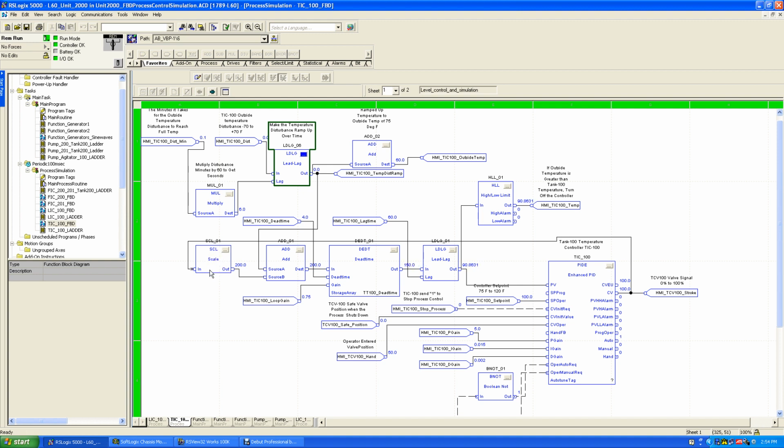So say it's 60 degrees outside and you've got the process at 100 degrees, and then all of a sudden a storm comes in, and it comes down to like 30 degrees. You're not going to be able to maintain that temperature. It's going to start dropping off and dropping off. So we add a disturbance, and we find out what the limitations of our energy going into our temperature is with our disturbance right here. So that shows how all these programs work.